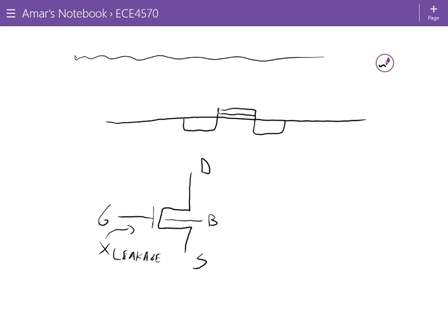But if you have a billion transistors on your chip and they're all leaking a little bit, that's going to increase your power consumption of your device. Leaking currents is kind of like a leaky faucet. You're going to require more current in the device. It's going to drain battery faster.